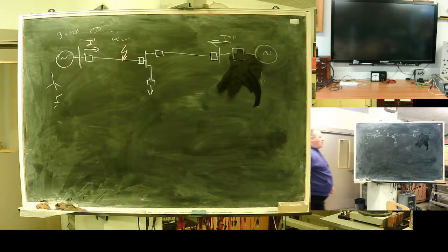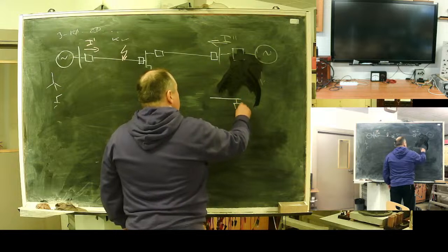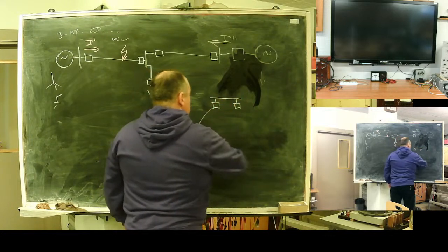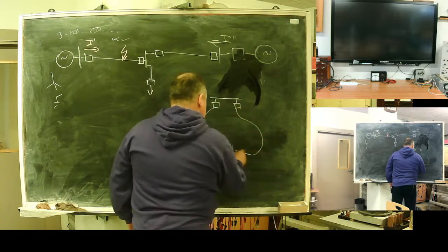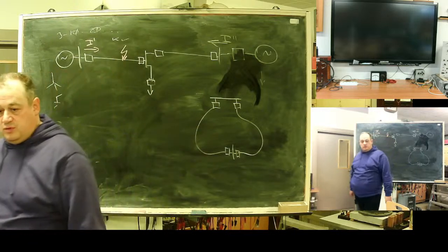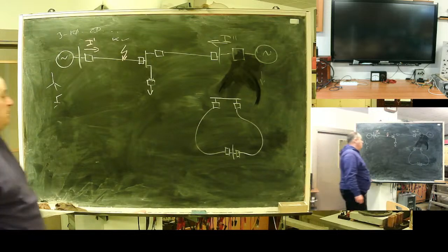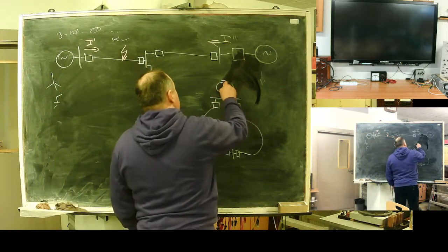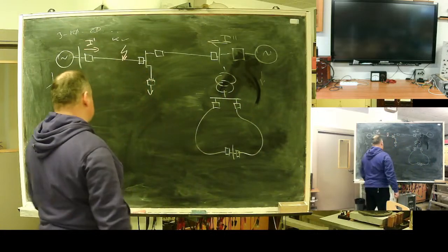First, they are more reliable. A very well known design is a ring type network where you can power each segment from two sides. This means that in case of repair work, you don't need to disconnect any customer. Here's the feeding transformer. Ring type networks.